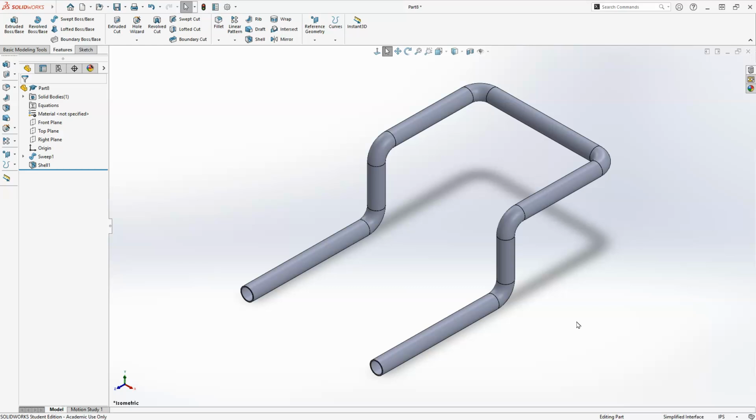Rather simple, right? So just remember that anytime you're creating that 3-dimensional sketch, just kind of follow it through. Don't try to do too many lines at one time. And the rest of the stuff is kind of self-explanatory with the shell command and the sweep command. But always remember, sweep, profile, and a path. Remember, when we do revolve, that's got to need a profile and an axis. And just an extrusion is nothing more than just a profile and you're giving it a distance.